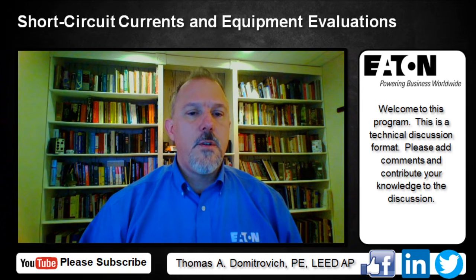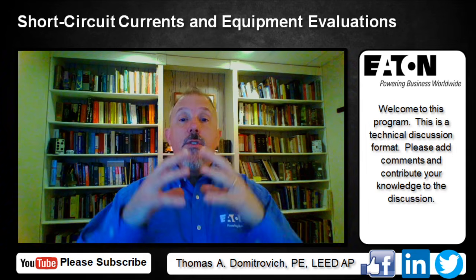If you don't need to know the short circuit current for fuses, how do you know what fuse to use? Okay, you size your fuses on what you are protecting. So if I have 300 amps worth of conductor, I'm protecting it at 300 amps. I'm not picking the fuse based upon the interrupting rating. I'm picking the fuse based upon the ampacity of the conductor that I need to protect per Article 240 of the National Electrical Code. I'm picking my fuse based upon if it's a transformer primary fuse or circuit breaker.